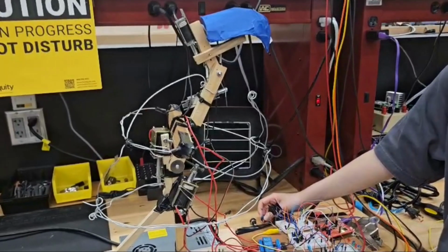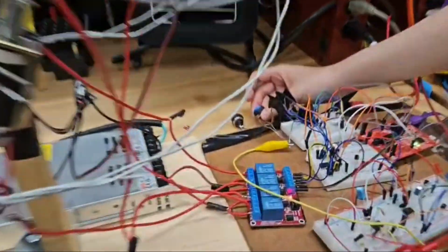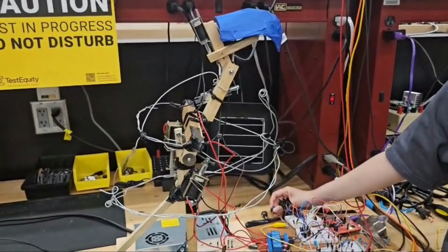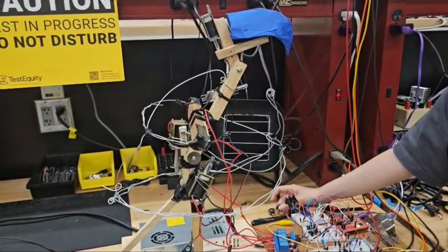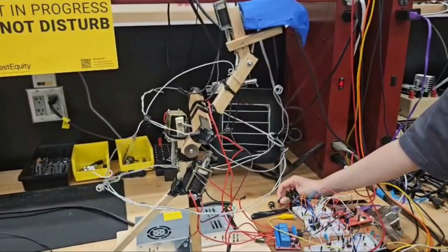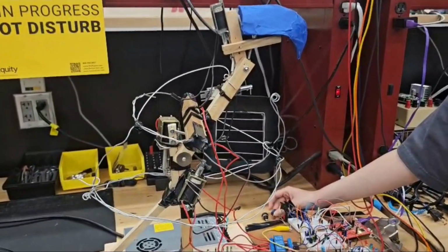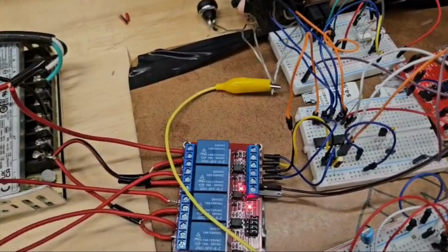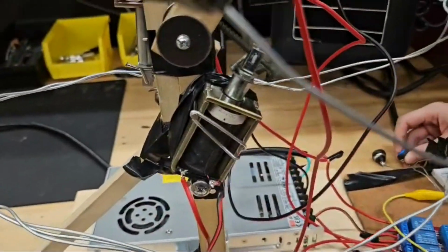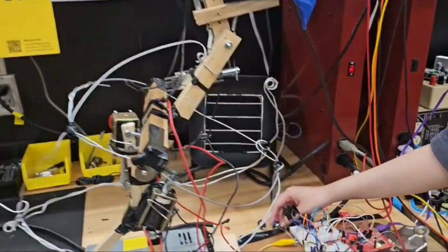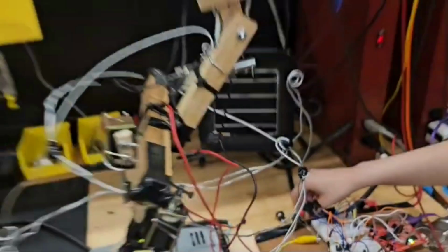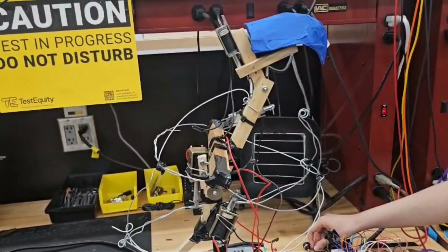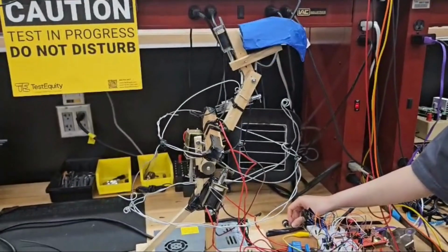So here's one of the mechanical issues we ran into regarding the body actuator. If we were to press the body button and hold it down and then release it, sometimes it goes back up, but sometimes when you press it and then release the button, the body doesn't mechanically retract. Now, if you press the body button, you can see the relay is clicking, the solenoid is actuating, but it is not moving. Whereas when you press, say, the head actuator, the body then retracts to its resting state. And now it works perfect. It works better with short pulses.